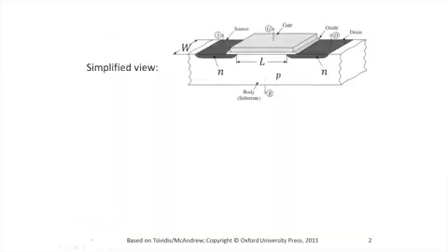So here you see a simplified view of the MOS transistor. It is built on a so-called P-type substrate, P-type meaning that it has a lot of positive mobile carriers, which are called holes, and which we will discuss later on. On top of which we diffuse two N-type regions. N-type meaning that they have a lot of negatively charged mobile electrons that are free to move and conduct electricity.